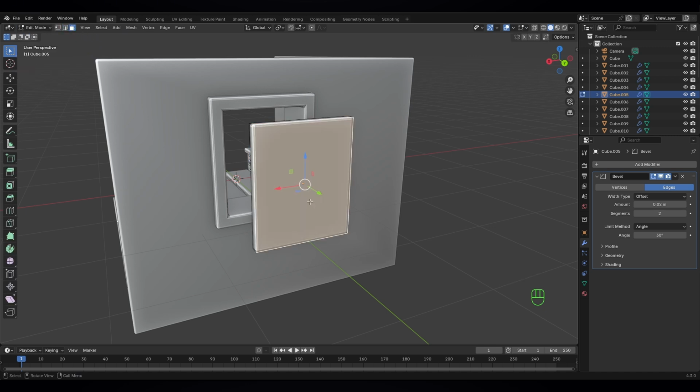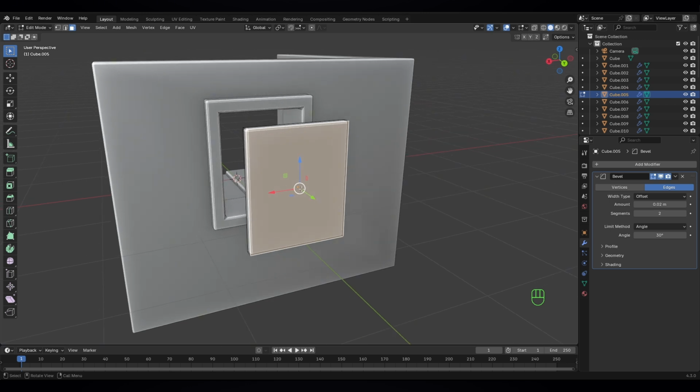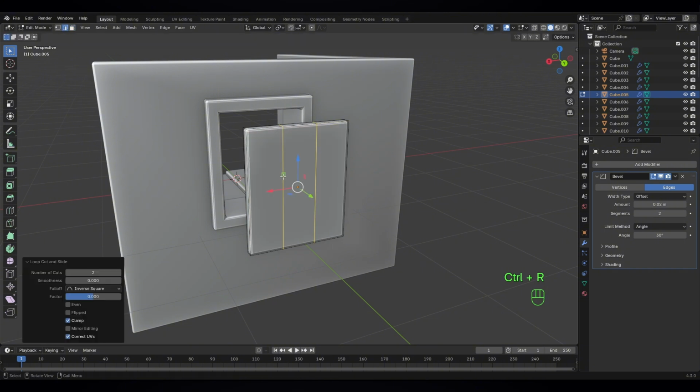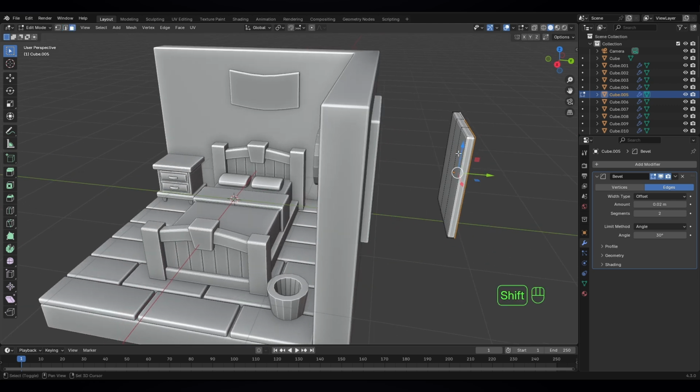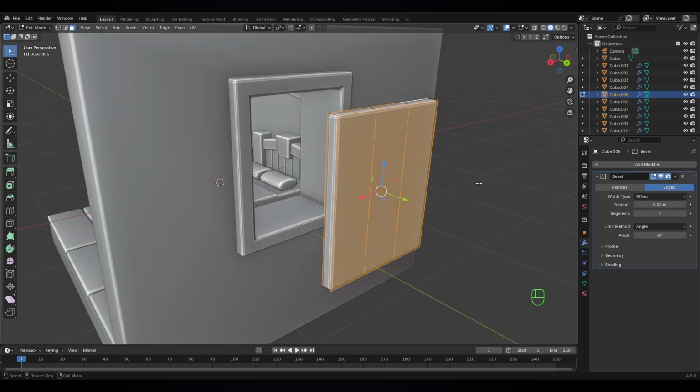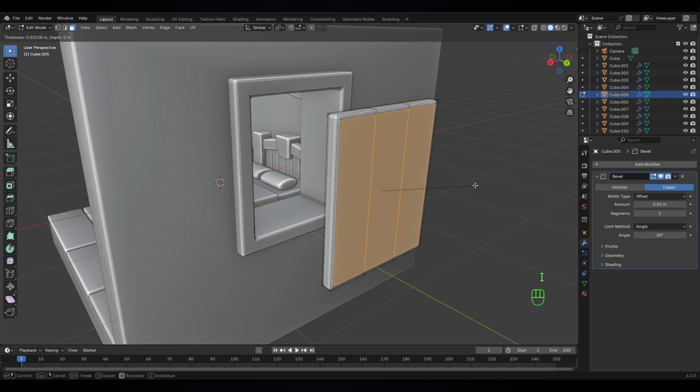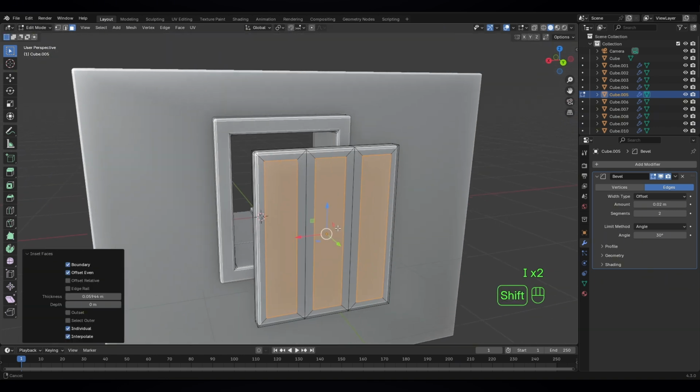Let's select this face. Okay, before that, let's give it a loop cut. I want to give 2 loop cuts here. This is going to be our windows place. Okay, just select the face and select these 3 faces and hold Shift and select these faces as well, and press I to insert. You see it's inserting this one. If you press I again, it can insert it individually. Something like this. That looks nice.